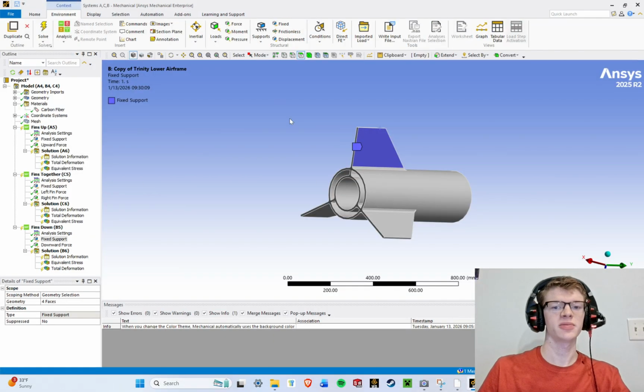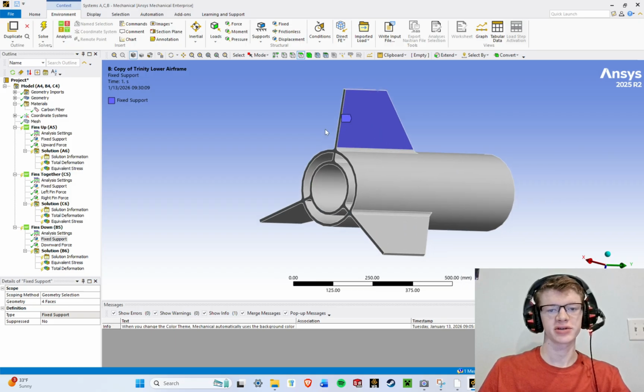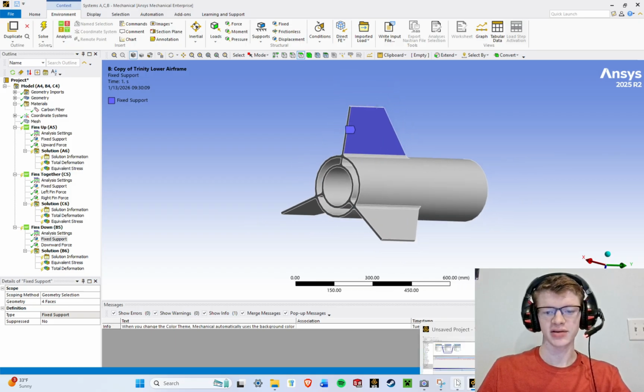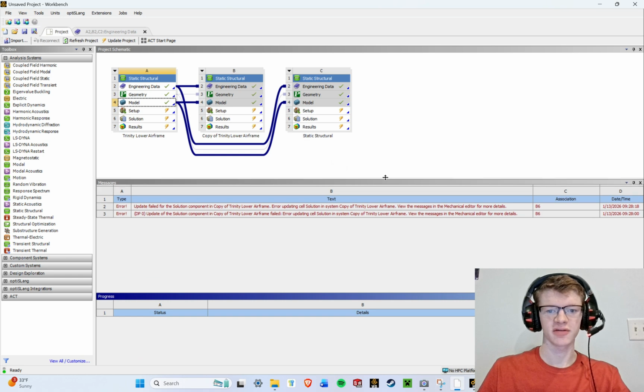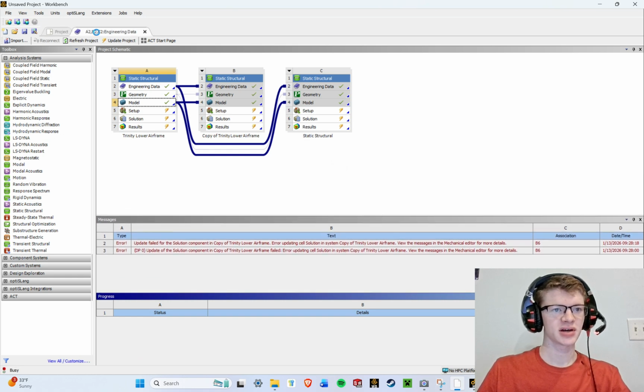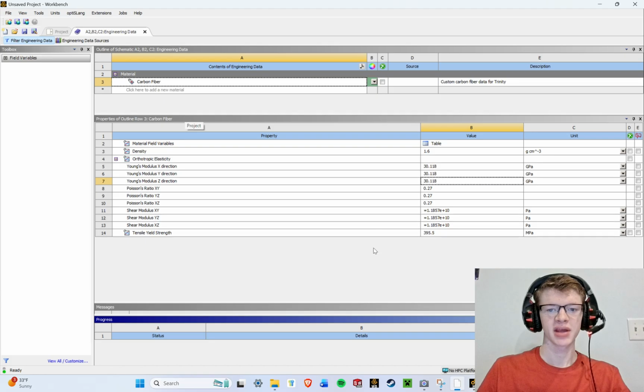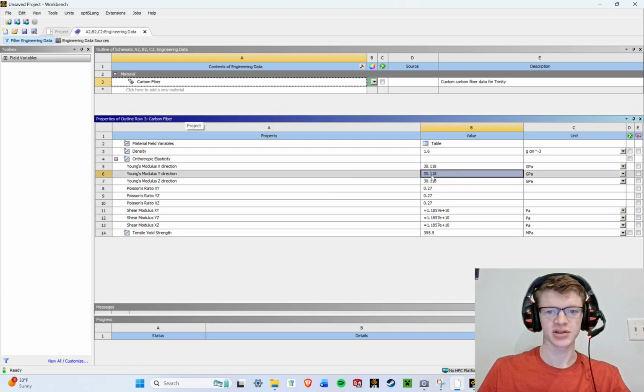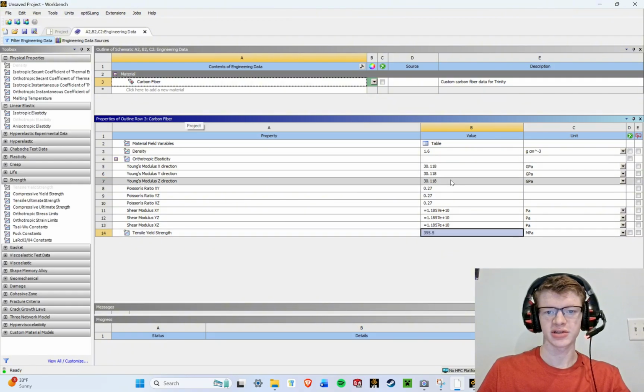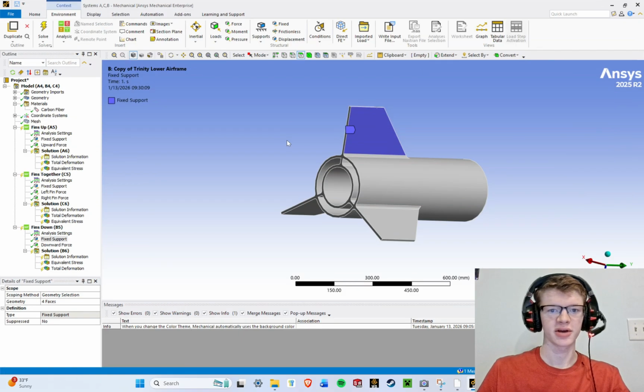Alrighty, a bit of a time loop here. I just tried to solve the model and it didn't work. Ansys was throwing a fit at me until I went back to the engineering data and I changed this from 32 to 30. So just change that and let's get on with the video.